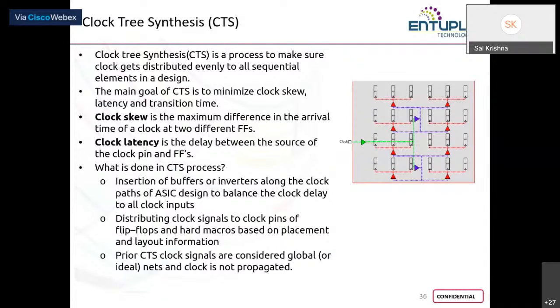So for a given technology node, the length and width of PMOS and NMOS will remain the same in an inverter. And because the buffer is nothing but two inverters in series, the same applies. But the problem is the majority carriers in PMOS are holes and the majority carriers in NMOS are electrons. And as all of you know, holes move slower than electrons.